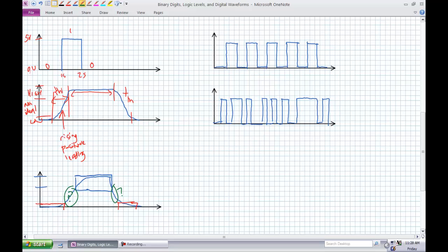The idea is to get those rising edges and falling edges to quickly and clearly transition from a 1 to a 0 and a 0 to a 1, so you're spending less time in the invalid region. You want to avoid those slowly creeping charging capacitors.